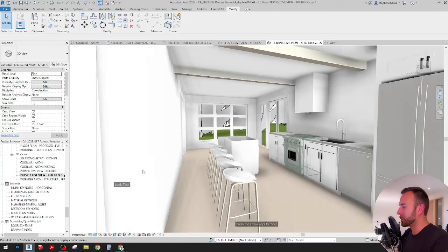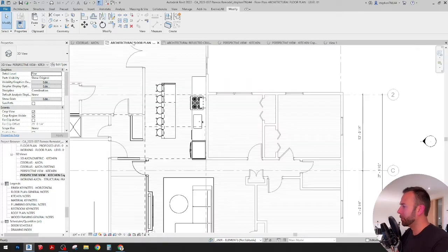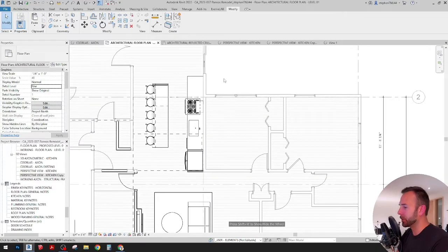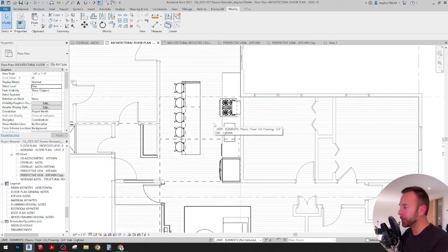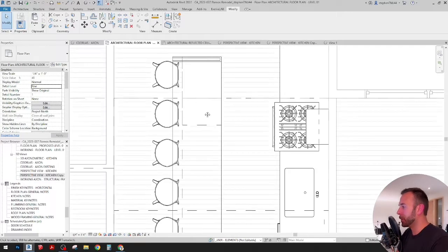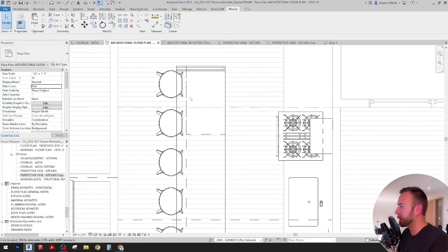So sometimes things on the plan look a lot more congested than they are in reality. That's especially true with bathrooms. A lot of the time my clients will feel like bathrooms look extremely small on the floor plan, and you'd be surprised at how small bathrooms need to be to fit the proper components. But anyway, as long as your structural items or non-movable furniture have the appropriate circulation space, you typically should be okay with circulation and navigation, things of that nature.